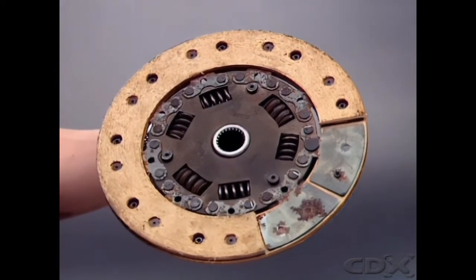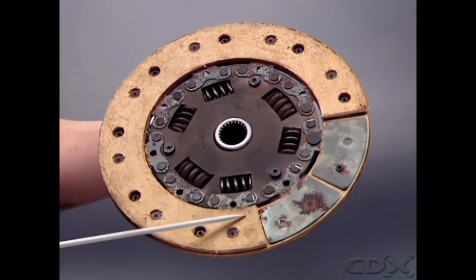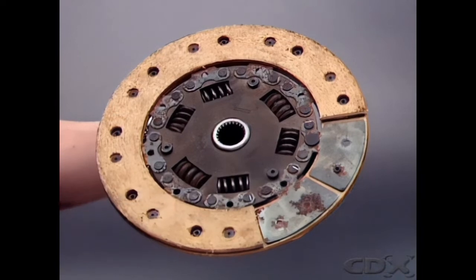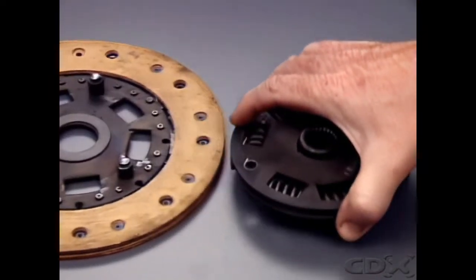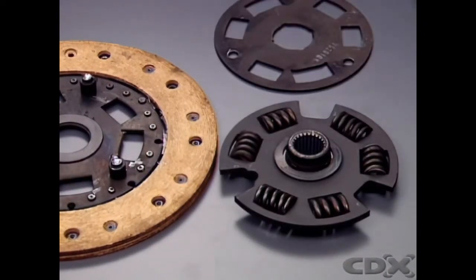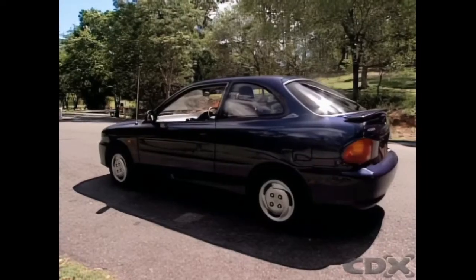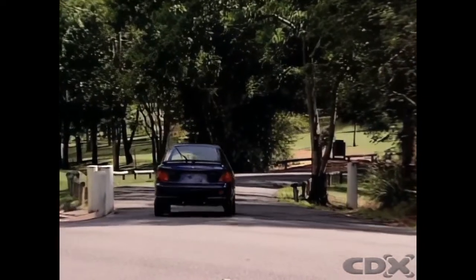The driven plate has a pair of friction facings, usually of wire-reinforced asbestos composition, carried on wavy spring steel segments, which are riveted to a steel disc. The central alloy steel splined hub is separate. Drive is transmitted from the disc to the hub through heavy torsional coil springs or rubber blocks. This spring hub arrangement dampens torsional vibrations from the engine. It also absorbs shock loads imposed on the driveline by sudden or violent clutch engagement.